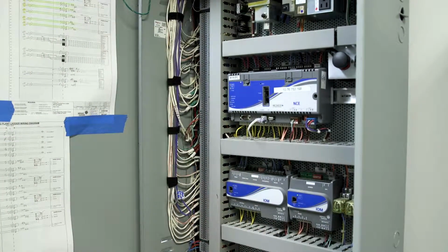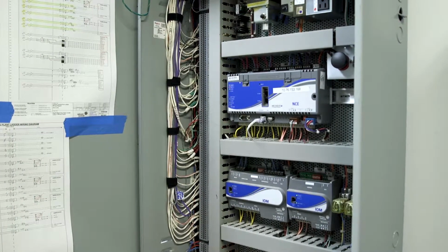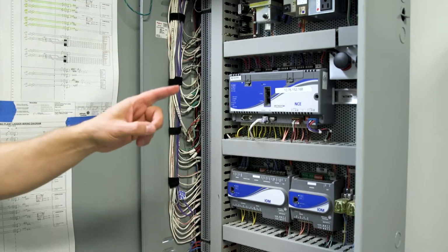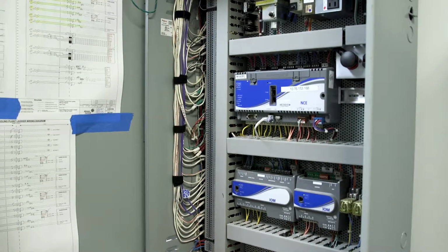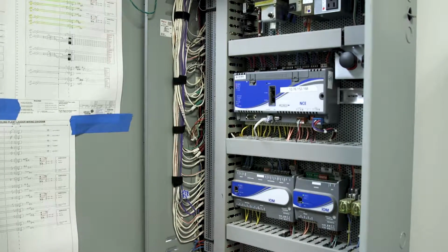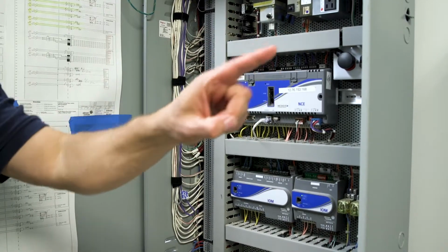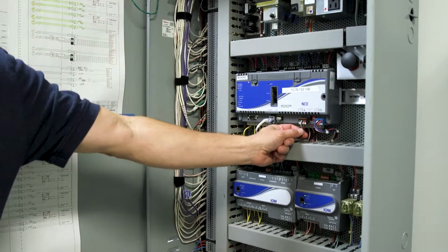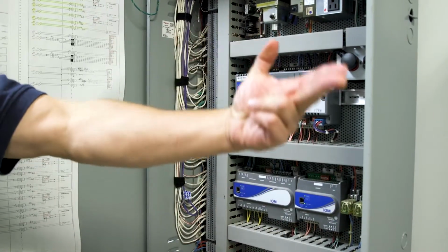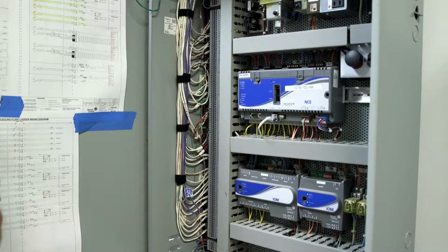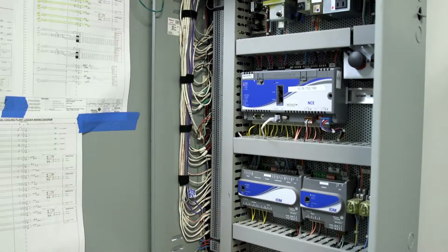You said that one has a 5,000 point limit? Yes, 5,000 points. The NCE and the NAE, which is in that panel. So it's 5,000 points or 99 per loop. And remember, the difference between the NAE and the NCE, this has one loop, the NAE has 2 loops. So when you're getting to the new building, they'll all be NAEs because we need those loops to get all those 485 VAV boxes in.